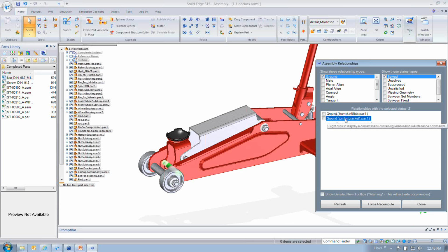I'm not sure what it is or what it's related to, but what I want to try to do is select this item, and I want to suppress that grounded relationship. So now I've got two relationships that I know that I intentionally suppressed. One's the grounded relationship of this pin we just did. And our workflow previously suppressed the angular relationship, which we really want to unsuppress and allow the variable change that we made from 5 to 20 to take place.